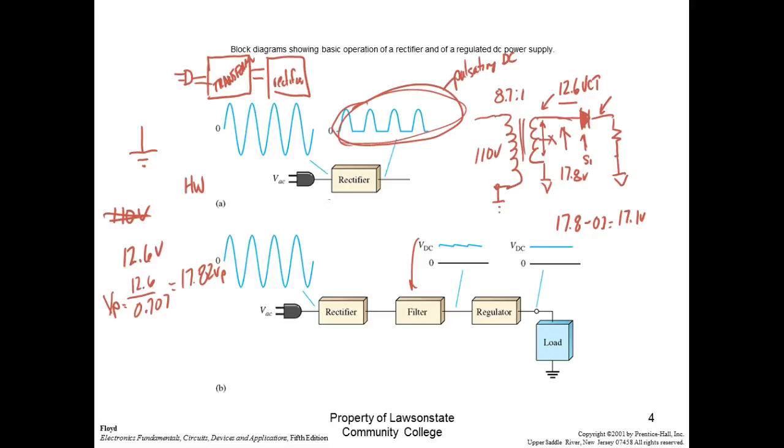Not yet, still DC. That's V peak out. Let me put my equation in. V peak out. So it says V peak out. Y'all see what it says, V peak out? V peak out is equal to what? Equation 13. V peak out halfway is equal to V peak out of the secondary minus the VF of the diode. Y'all understand that equation?